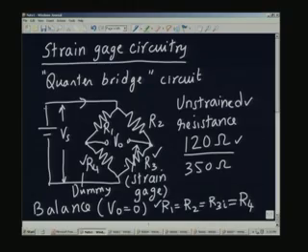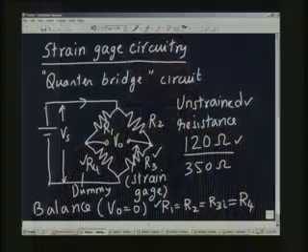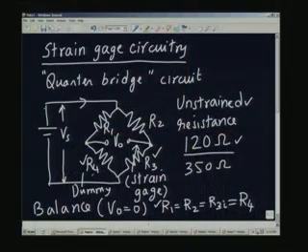These two, whatever changes take place, they will cancel each other. That is a very important thing. You should put it in the arms like this, R3 and R4. If you put the dummy gauge here and the actual gauge here, these effects will more or less nullify.